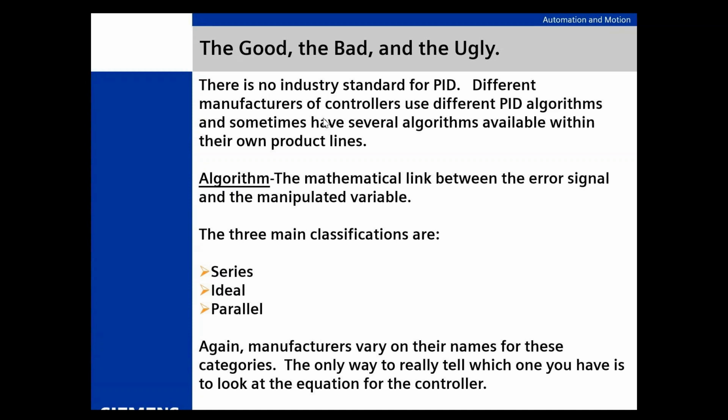I just don't see that. Like I said, in the old days, if I had to manually tune a controller and I was replacing something else, the first place I started was whatever PIDs were in that original controller. If the customer was happy with that, let's start there. And most of the time, that was pretty close to being dead on. So I cannot see the algorithms being wildly different.